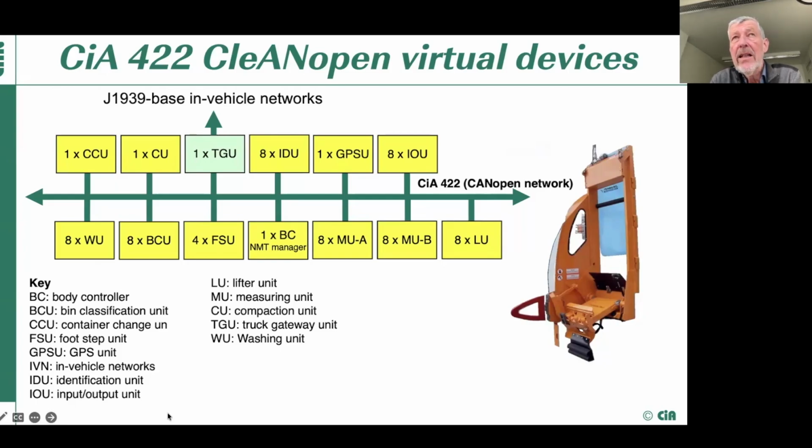So you have the entire functionality of CANopen available on the J1939 network, and we can configure and communicate with the virtual devices as in CANopen. There is a request which you have as a user, which profile should be mapped, and then we just need to request parameter group numbers for the PDO related parameter groups, to make it clear. But we can do more.